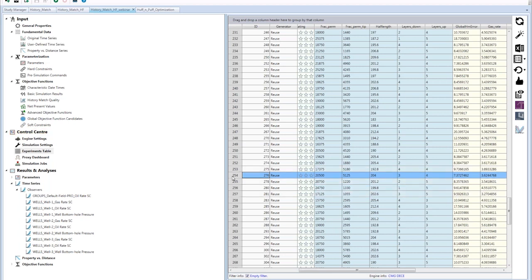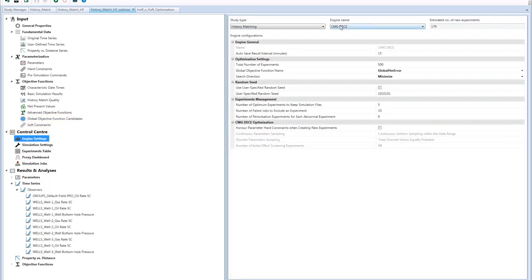Okay. The next question is, how would changing the AI algorithm help in either history matching or optimization? As Jeremy showed, there are several AI and machine learning algorithms inside CMOST. Now, it depends on the type of history match you want, whether you want a single history match or multiple history matches which meet your acceptable criteria, and on which engine you use, like particle swarm or the neural network optimizer, which is a new one in the recent version of CMOST.